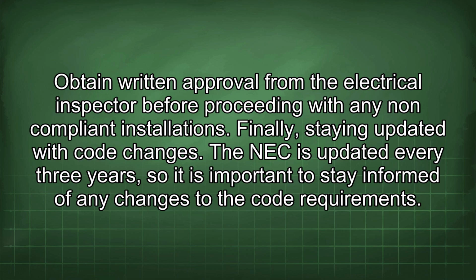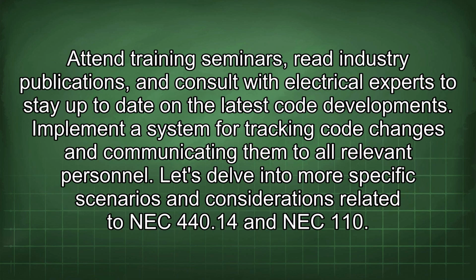Finally, staying updated with code changes. The NEC is updated every 3 years, so it is important to stay informed of any changes to the code requirements. Attend training seminars, read industry publications, and consult with electrical experts to stay up to date on the latest code developments. Implement a system for tracking code changes and communicating them to all relevant personnel.